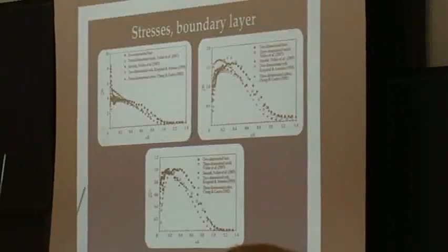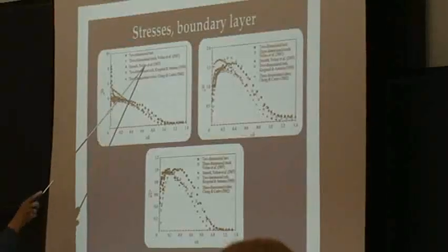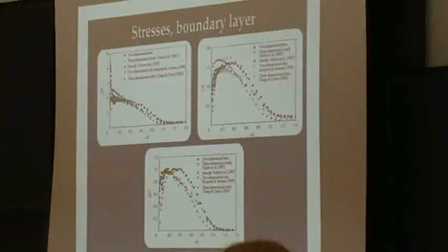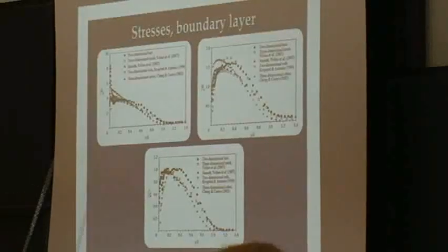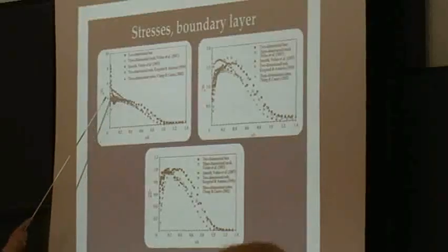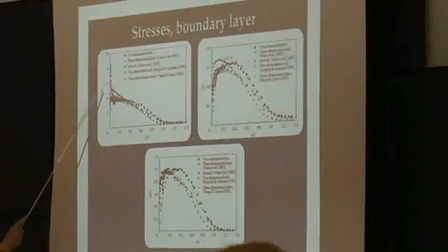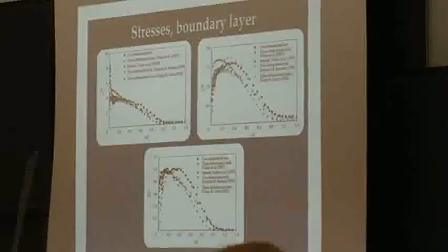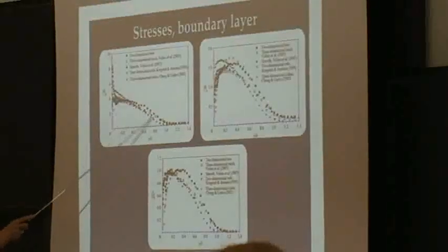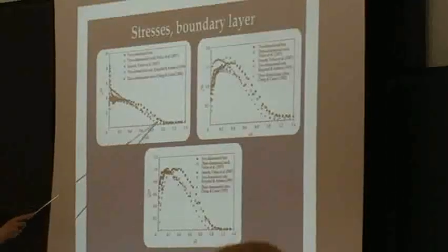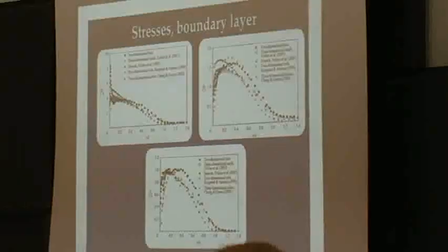we have the data by Molino, Schultz, and Flack, which tended to show exactly the same, or in fact even larger effects, because we said that there should be very little effect on U squared in the outer layer, but they produce a significant increase from the smooth wall data to the rough wall data, also in the outer layer.